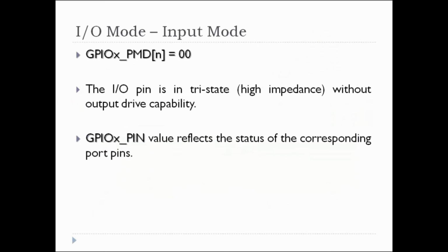Now we will see the IO modes in detail. If you want to configure the IO mode, the value for GPIOX_PMD for that particular 2 bits decides it. Each one is a 32-bit register, and each 2 bits represent 1 pin.